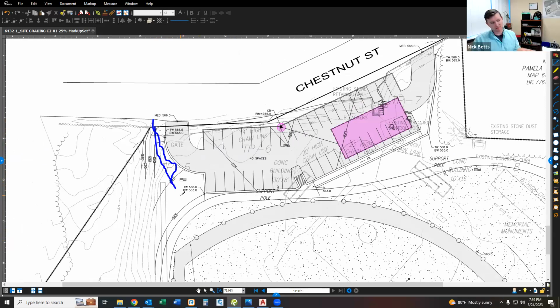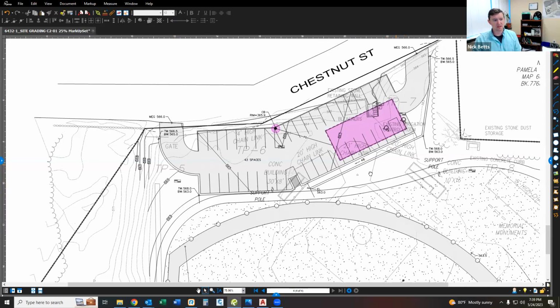We're thinking of this access, that's about 15 or 16 feet wide. So if we needed to make some sort of emergency vehicle access, we could get it down here at a reasonable slope. That way, if an ambulance or someone needed to drive down to the field, they could bypass the parking lot and just drive down the grass. They have plastic grid systems that you put down in the grass to make sure that they can take the weight of the trucks.